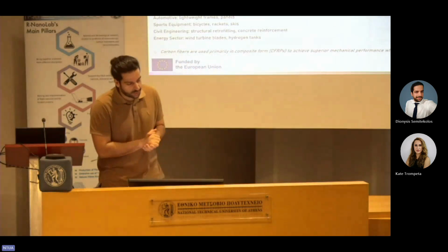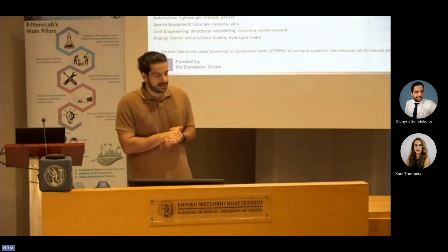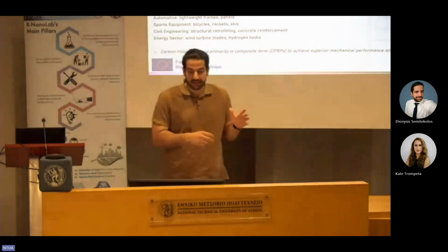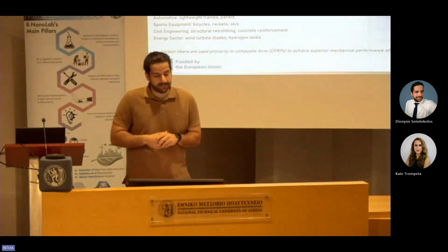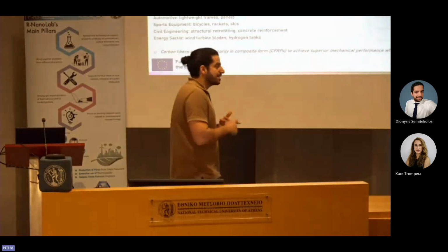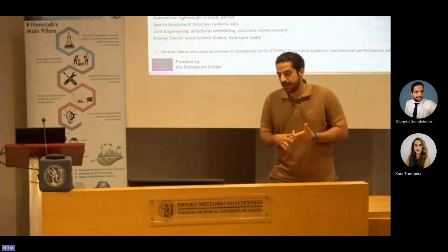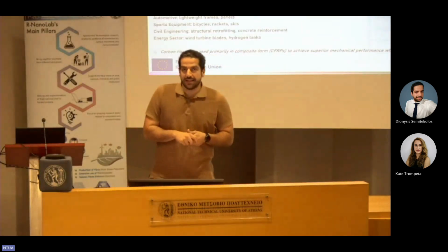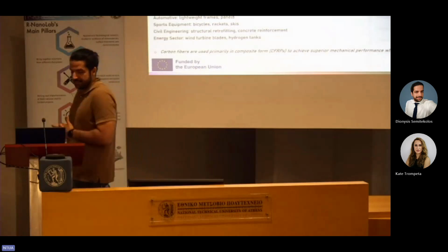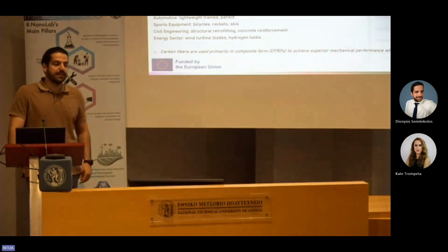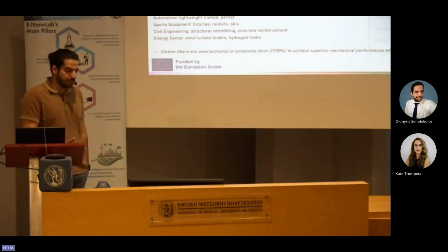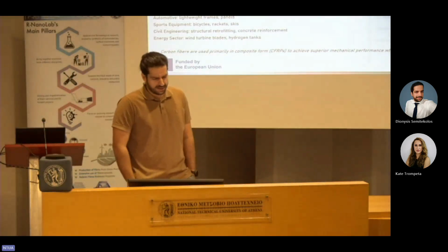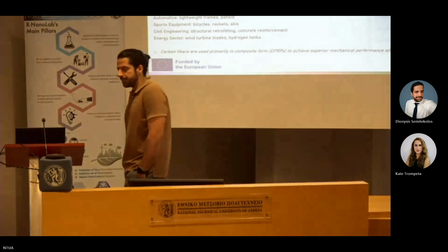And we can see this also from some of their key characteristics, like the density, which is around 1.75 grams per cubic centimeter, a tensile strength that can go up to 7 gigapascal, and a modulus that can go up to 900 gigapascal. They are also chemically inert and very stable thermally, because they are composed mostly of carbon. Carbon has superb thermal stability in this form.